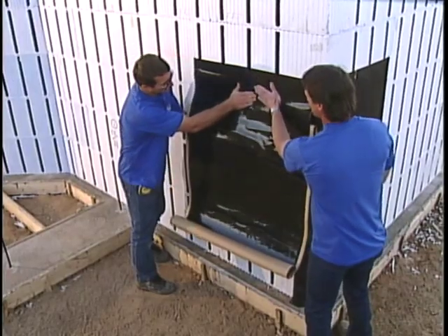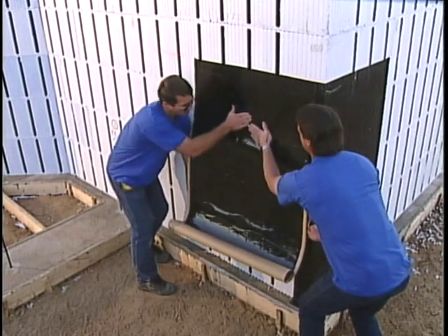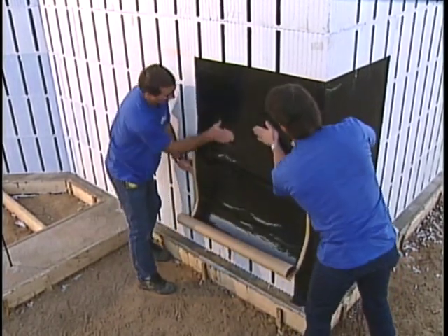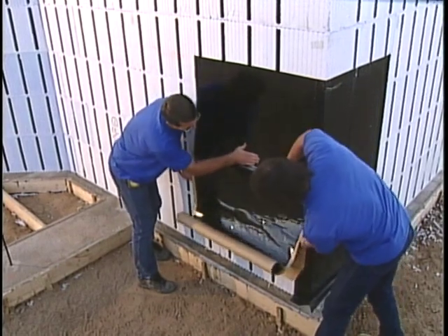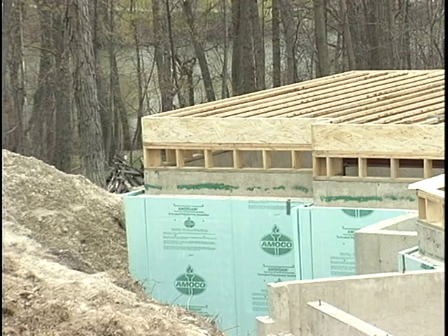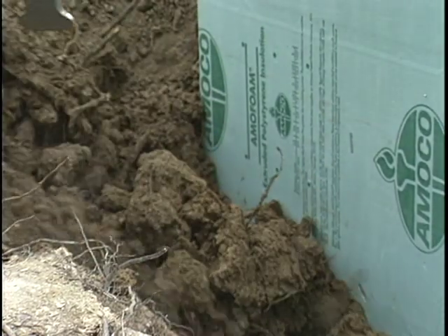With cavity wall construction, the forms themselves serve to insulate the poured concrete wall. Waterproofing can be done by applying a self-stick rubberized membrane to the outside of the styrofoam outer surface. After the foundation is cured and waterproofing has been completed, the excavation outside the walls must be refilled with earth. This is known as backfilling.